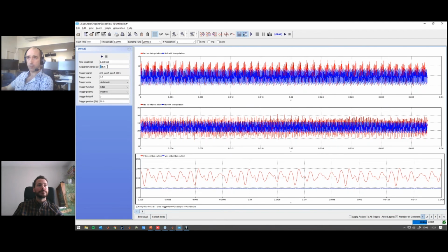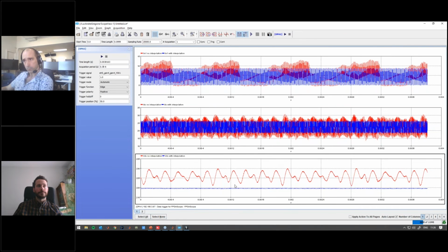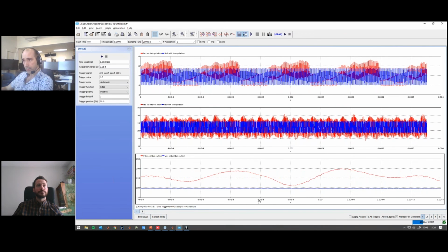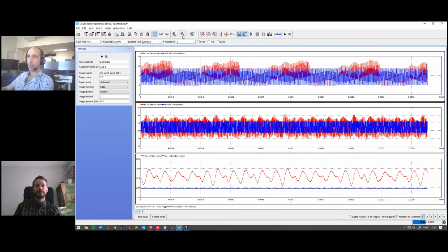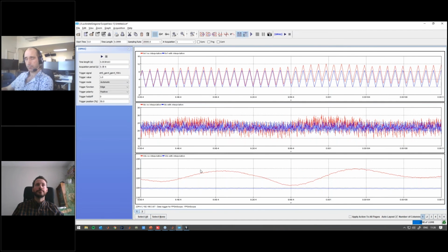So if we go to the full bandwidth that we can achieve, like this, now you can see that it's still 5 kilohertz, but there is more oscillation all over the signal. And so basically aliasing is a fancy way to say that you don't have all the information to properly represent the signal in the simulation or in the control. I don't know if it answers.